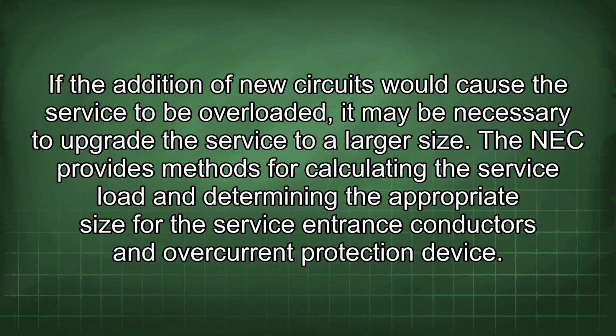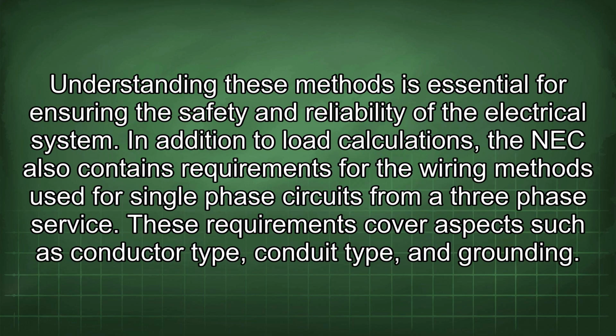The NEC provides methods for calculating the service load and determining the appropriate size for the service entrance conductors and overcurrent protection device. Understanding these methods is essential for ensuring the safety and reliability of the electrical system. In addition to load calculations, the NEC also contains requirements for the wiring methods used for single-phase circuits from a three-phase service. These requirements cover aspects such as conductor type, conduit type, and grounding.